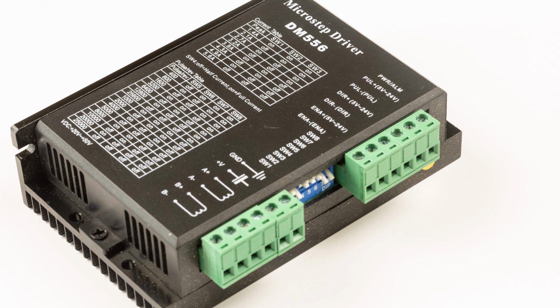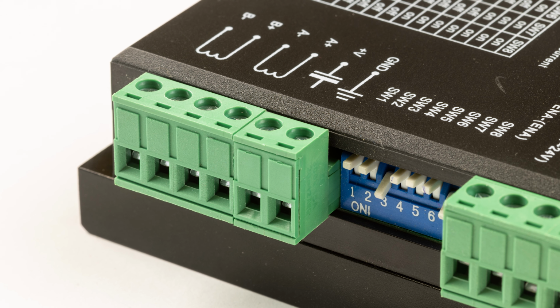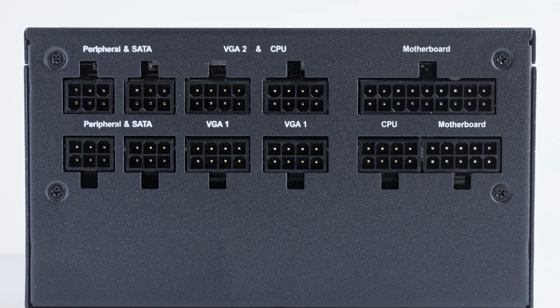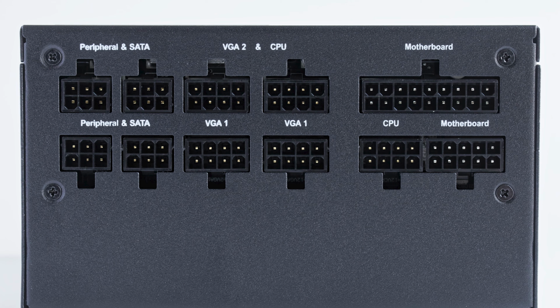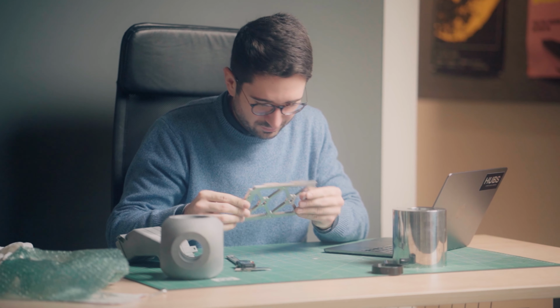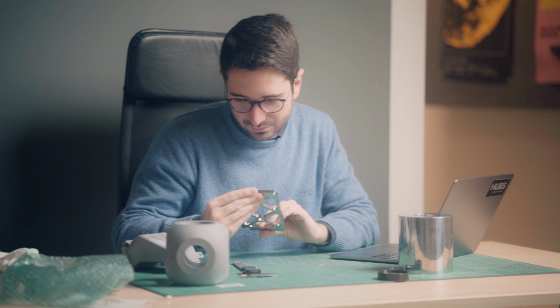Create modules that can be combined in different ways to create various products. For example, use a standard motor module that can be integrated into different product lines. Design standardized interfaces for modules to ensure they can be easily connected or assembled in different configurations. Review each part to determine if it is essential to the product's functionality, and if not, remove or combine non-essential parts.